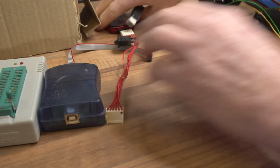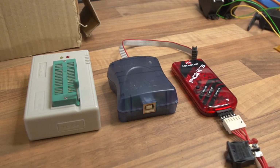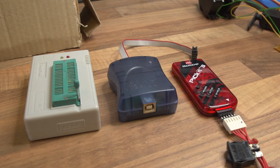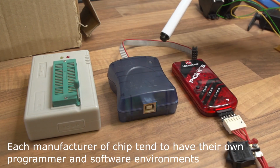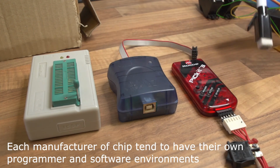So there's a few different programming devices, and I use all three personally, depending on what it is that I'm actually working on. They all have their own purposes. There are other programmers as well for different devices. The STM, they have their own system. A lot of the STM microcontrollers you can program through USB. You don't really need any external programmer at all, but you can program with their own dedicated programmers. You tend to find that each manufacturer of chip has their own method of programming the chip, so you end up with a collection of programmers if you're using different chips. But these are probably the common ones, I would say.